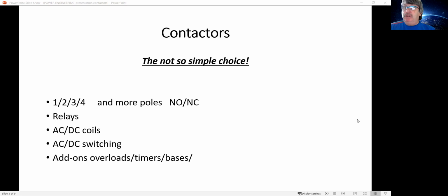Of course, there are specialist types of contactors, and we'll call those relays. These are generally in the switching level of things, not so much in the power consumption area. They are there to generate signals on and off, switching and closing contacts to make a process operate.